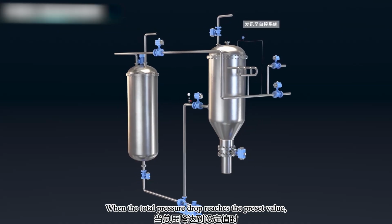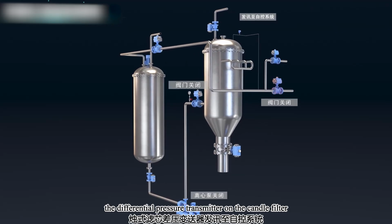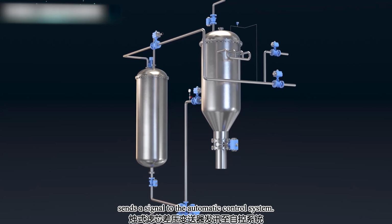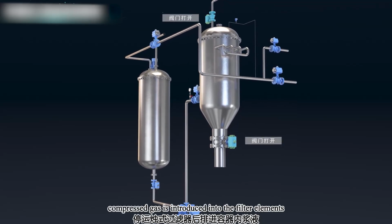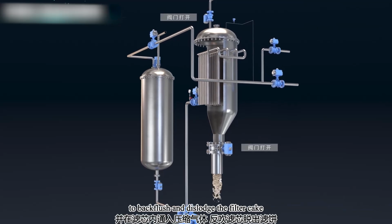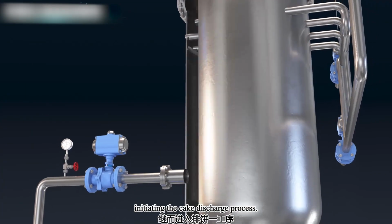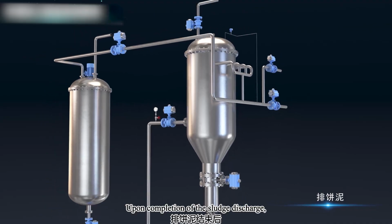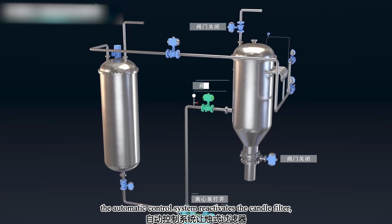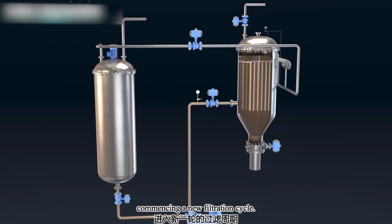When the total pressure drop reaches the preset value, the differential pressure transmitter on the candle filter sends a signal to the automatic control system. Subsequently, compressed gas is introduced into the filter elements to backflush and dislodge the filter cake, initiating the cake discharge process. Upon completion of the sludge discharge, the automatic control system reactivates the candle filter, commencing a new filtration cycle.